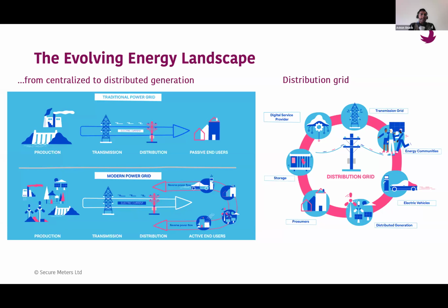That is the first part. The second thing is the quality of the power, because solar or wind farms are not a constant source of power compared to the traditional fossil fuel based generating station, which runs at a constant frequency. In the case of renewable resources, it's not constant. Solar generation depends upon the intensity of light, whether it's cloudy or not. Wind depends upon the wind speed. So the power coming into the system is variable, and it's very difficult to manage the power quality. So these are the challenges. And also, apart from that, we have the storage.